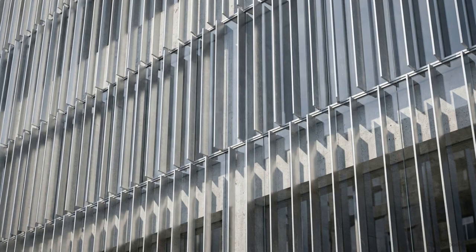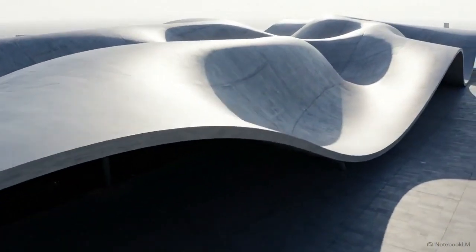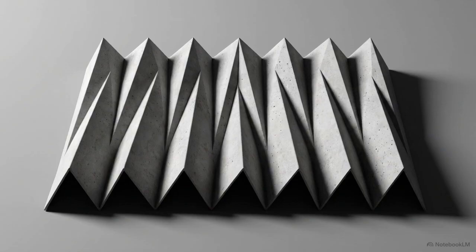We now shift our focus from heavy volumetric massing to the manipulation of lightweight planar elements. These specific operations are strictly utilized for defining building envelopes, dynamic facades, distinct roof structures, or floor plates. Starting with this flat rectangular plane, we apply a fold to bend it sharply in half. By repeating the action, we pleat the surface into an accordion-style zigzag texture, establishing structural rhythm.